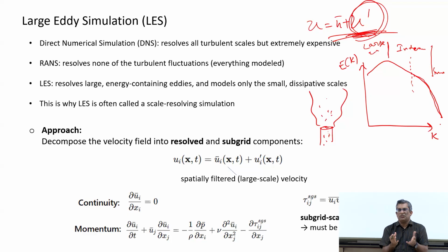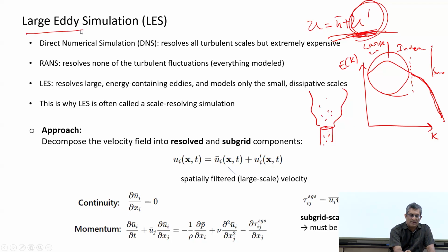What will affect is only Reynolds number. So based on this assumption, you assume that, okay, this is prescribed, so I don't have to bother about it, and you prescribe this through some model, and what you resolve is only this part, mainly the large eddies. So that is why its name is large eddy simulation. You resolve the large eddies. And LES is often called a scale resolving simulation.